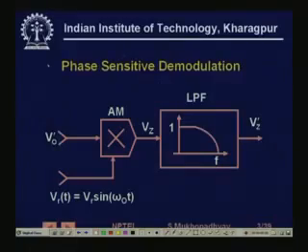Now, this change in capacitance, we have also seen that typically there are two capacitances, and if one capacitor becomes C naught plus delta C, the configuration is made such that the other capacitor becomes C naught minus delta C. Typically, if you have two fixed plates and a parallel plate in the middle, and you have terminals from here and here and here, you actually form two capacitances.